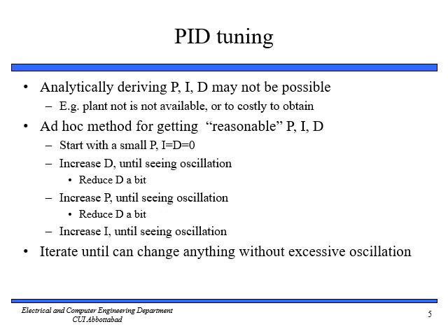So until now we have discussed controller design based on a model of a plant. P, I and D values could therefore be determined through quantitative analysis. As I have told you previously, if we have the model of the plant, we can determine the values of P, I and D. In many cases, however, quantitatively determining PID values is not necessary. In particular cases where safety is not a concern and the cost of using the plant is not a major concern either, we can select PID values through a somewhat hit and trial method. So if you do not have a system with safety concerns, we can just tune the PID parameters with the help of hit and trial.